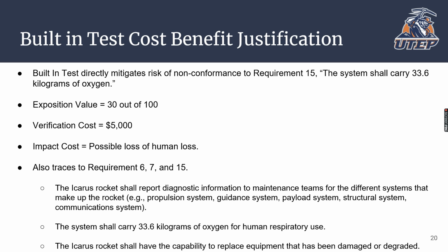The benefit justification for pursuing this built-in test is that it mitigates the risk of non-conformance to requirement 15, which is the system shall carry 33.6 kilograms of oxygen. If this was not conformed to, then there'd be a lack of oxygen to the passengers, which can lead to the loss of life. We can see the reasoning behind this in our cost benefits analysis.